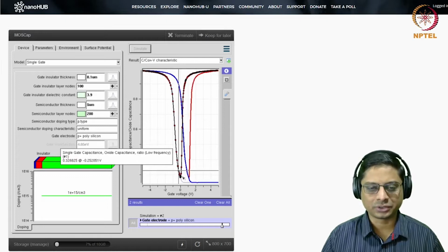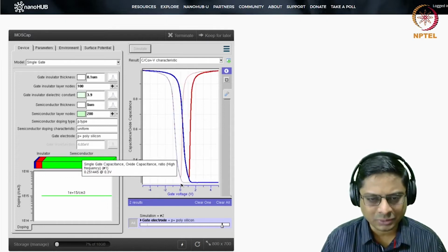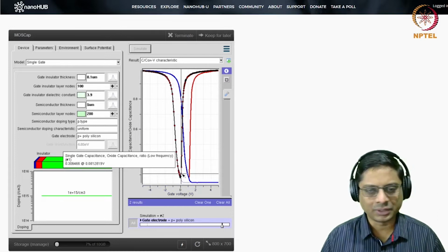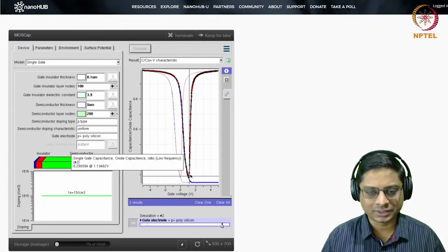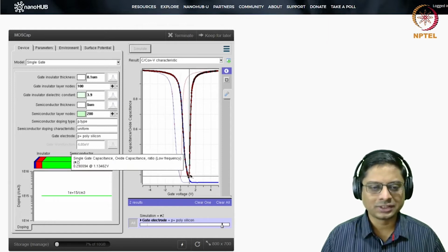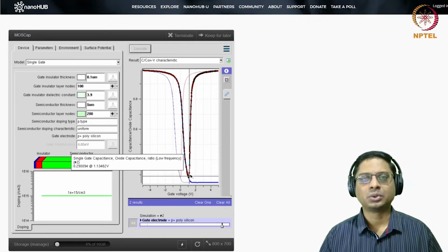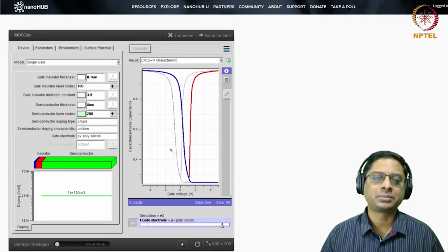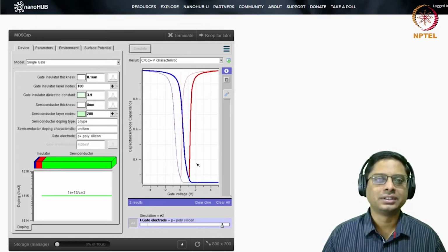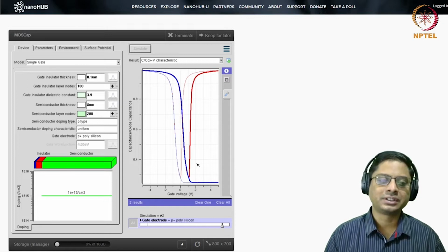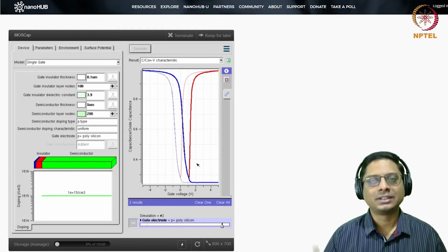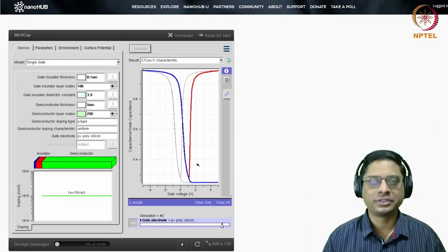You see that there is a shift. So the first one we saw the Vt was around 50 millivolts. I'm just taking the point where it's starting to go up. So okay, 50 to 80 millivolts. But when you look at the second simulation where I use P plus poly, the Vt is about 1.1 to 1.2 volts. So you see this Vt shift. You should be able to explain why this is happening, right? So essentially the phi ms was negative in the case when I'm using N plus poly and P-type substrate, and that is actually pulling down the overall magnitude of Vt.